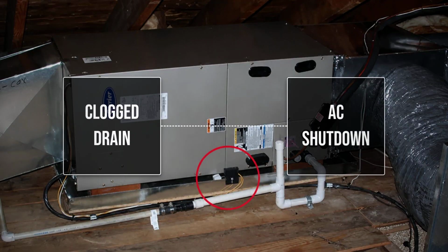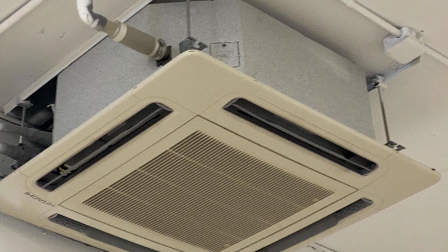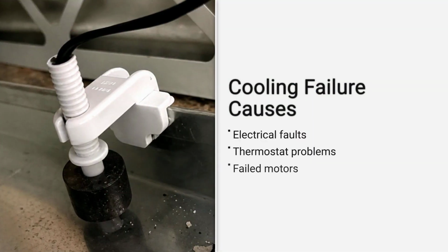Carrier explains that a safety float switch can shut the air conditioner down when a clogged drain causes water to rise in the pan. The switch is there to reduce the chance that condensate spills into a ceiling, wall, floor, or equipment cabinet. That protective shutdown can remove cooling until drainage is restored. Electrical faults, thermostat problems, failed motors, refrigerant issues, and other conditions can also stop cooling.